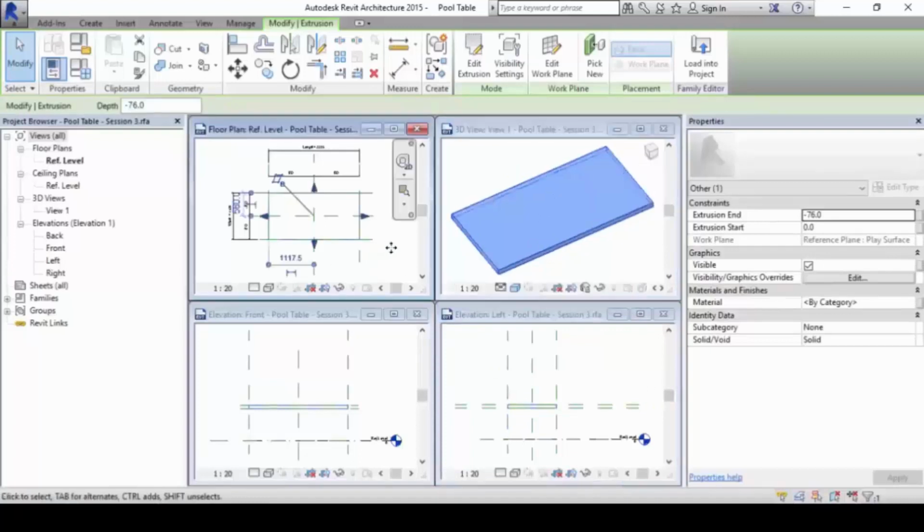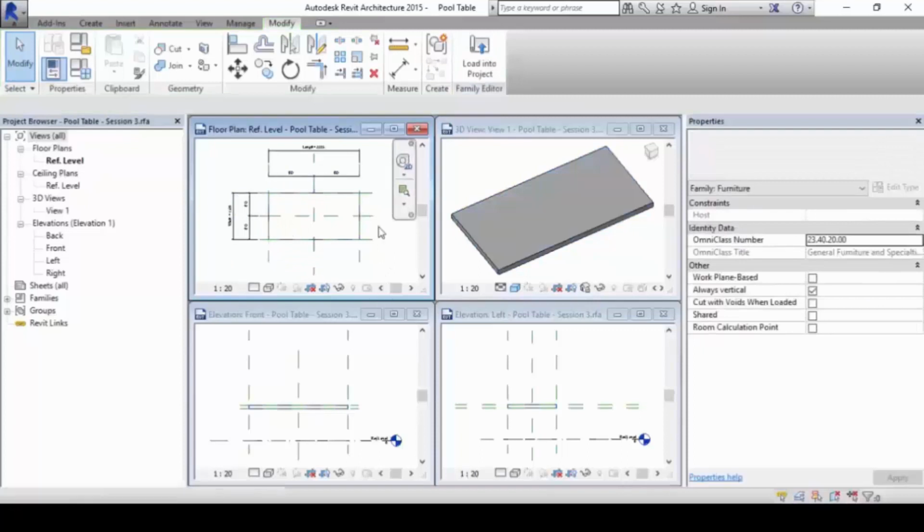However, in 3D Studio Max, you will find that when you hide an object, the object is hidden away in all 4 views. But in Revit, when you hide away that one object, it is view dependent. That means it only disappears in that particular view. The rest of the 3 views remains visible. This part. Okay. So we are very careful here.